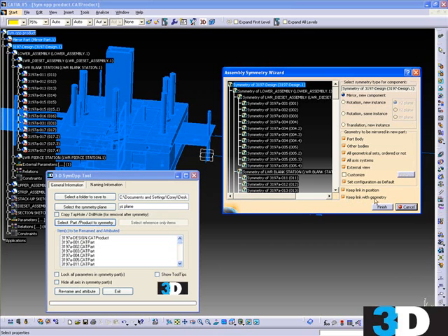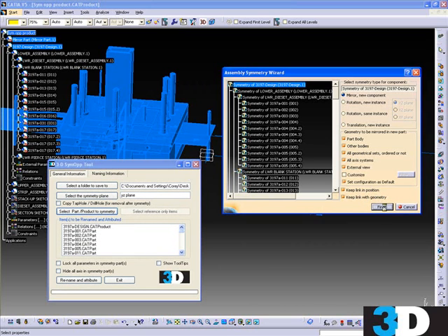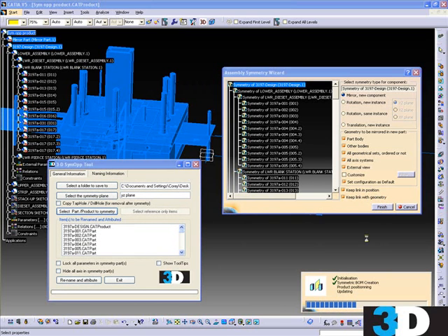You can keep link in position and keep link with geometry if you want to be able to have future updates. If you wanted to isolate it at this time, you could uncheck those boxes. However, I'd recommend still keeping those. And what we're going to do is just hit finish here. That's going to complete the Symmetry process.